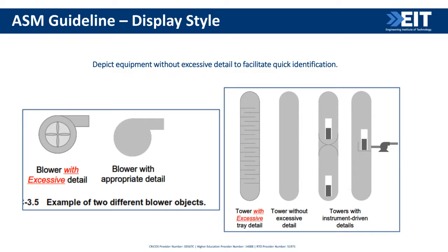I was a graduate engineer many years ago, and I used to take quite a lot of happiness and feel proud whenever I animated displays. I used to like seeing these impellers actually rotate. But over the years, it was found that it is not going to add any value to the operator. It is only going to be more of a distraction, and reducing the amount of unwanted information on a display actually aids in a better response from the operator.